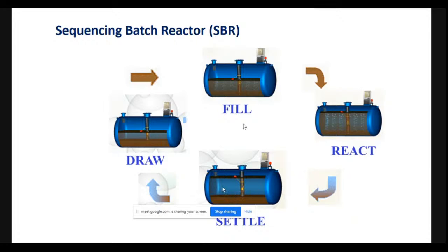All right. So you have the liquid in the tank, and in the first case, you remove as much water as can be removed from there. So what happens at the bottom of the tank? As the level of the sludge increases, there's a mechanism that automatically rejects those excess solids, and that will be mixed into the primary tank where it is filled, so that you get the sludge activated with the microorganisms, and then you can see that the treatment efficiency is more.